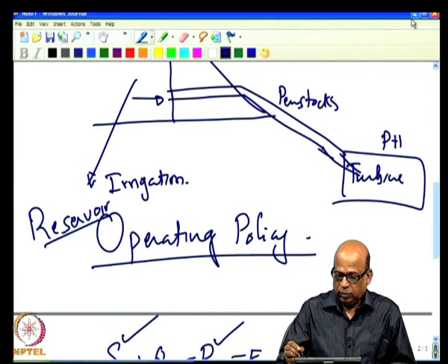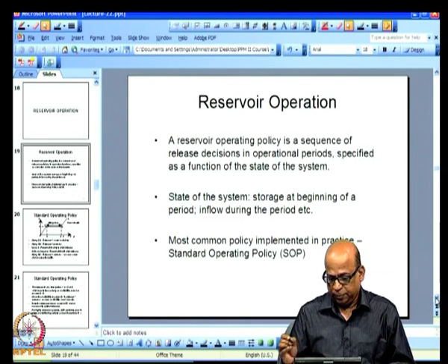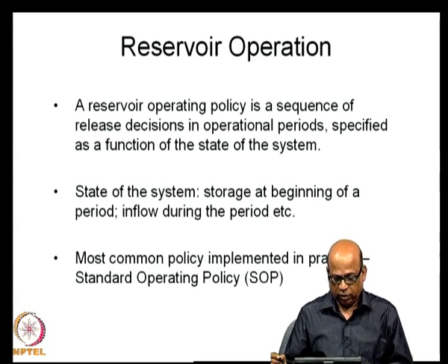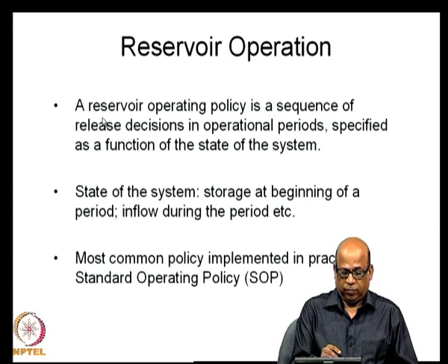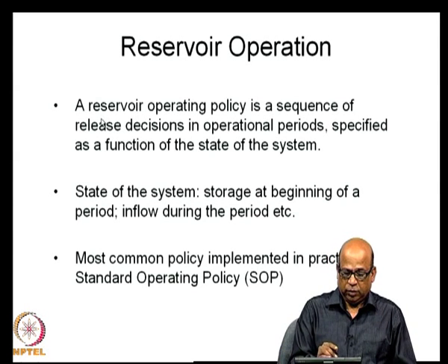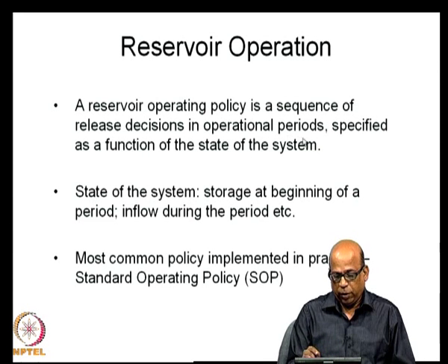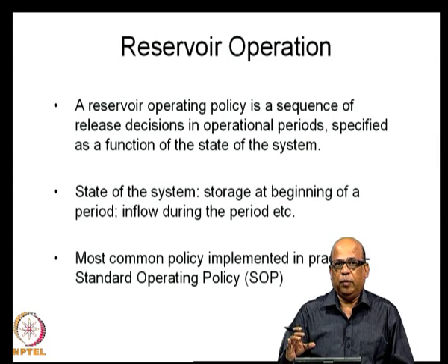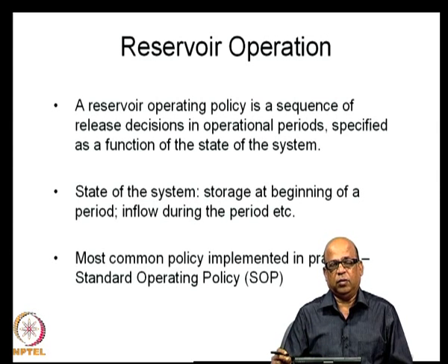We will start with the most commonly used reservoir operating policy, which is the so called standard operating policy. So, we will formally define now what we mean by a reservoir operating policy. Reservoir operating policy is a sequence of release decisions in operational periods. Now, these operational periods can be different depending on the purpose for which you operate the system. It can be 10-day periods. For example, in irrigation systems, you may operate typically for 10-day time periods.